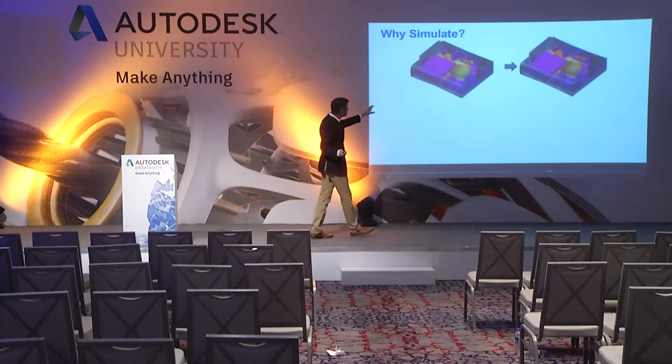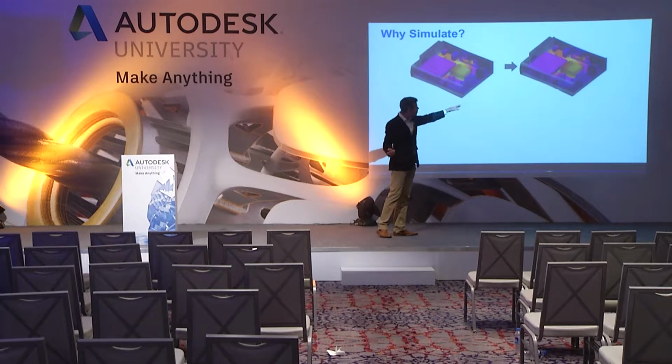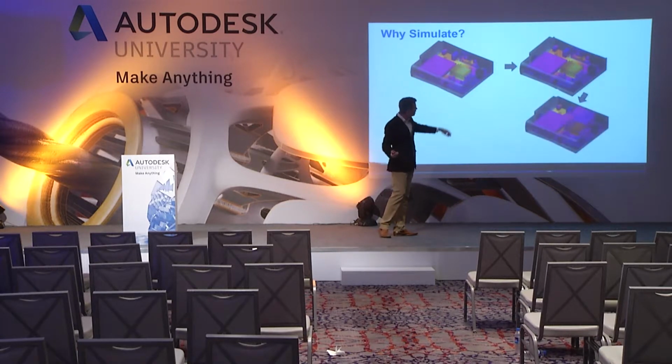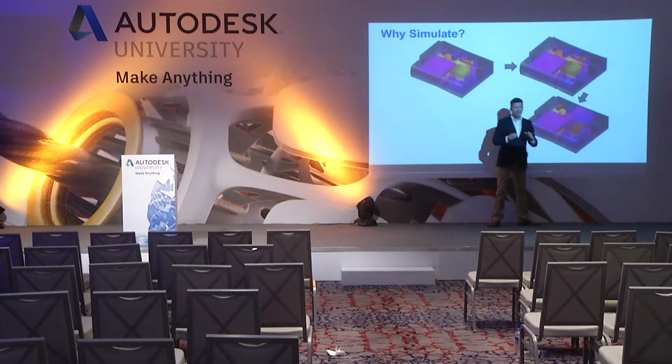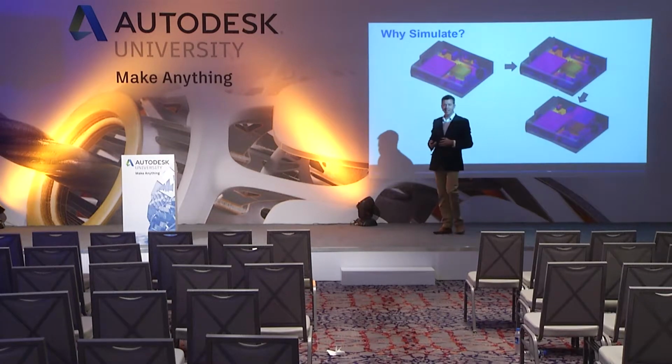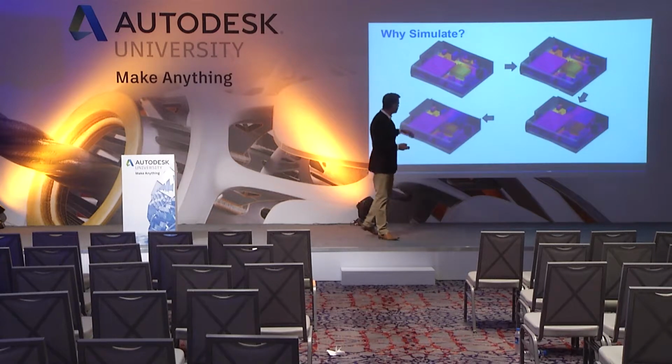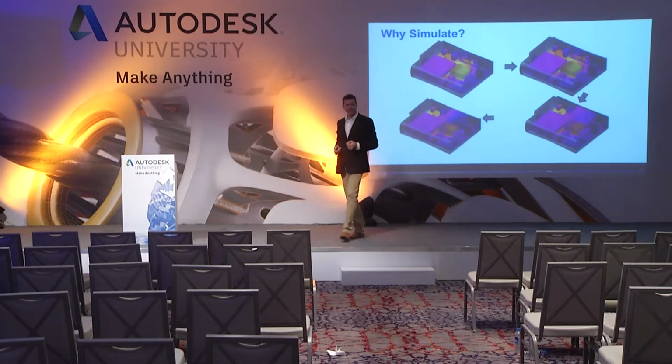So here we have the original design, a second design where the ventilation has been moved slightly, a third design which incorporates an enclosure to guide the airflow over the heatsink, and then there was another design where they looked at a different design of heatsink. So it was actually the third design that helped resolve the issues.